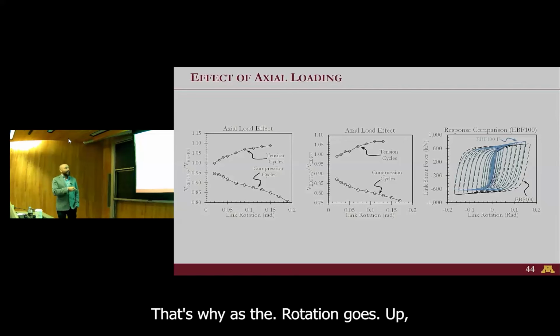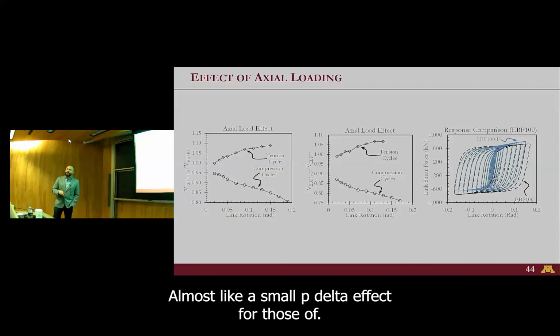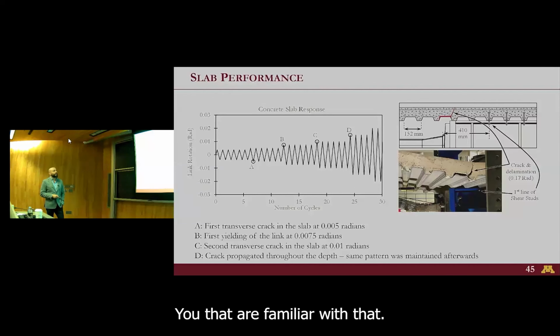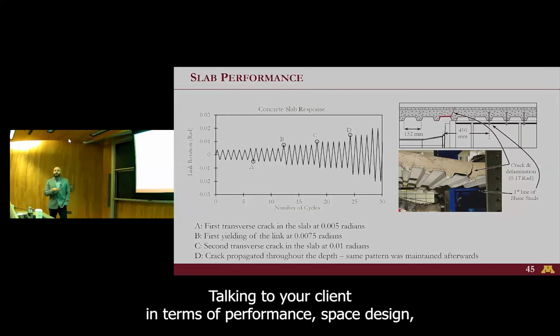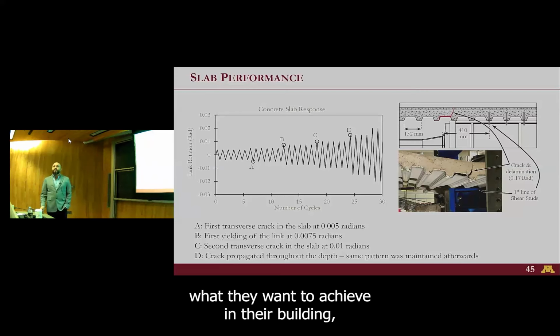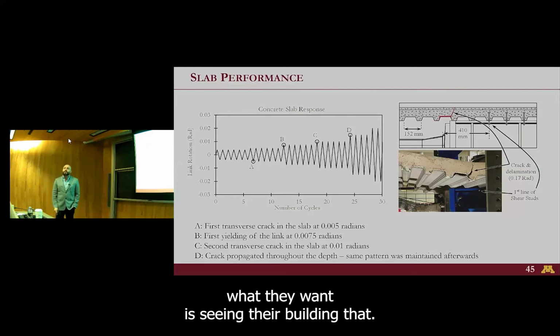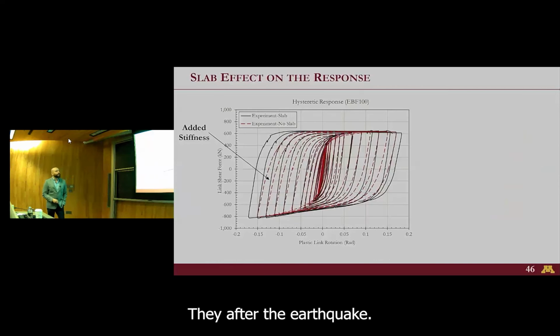That's why as the rotation goes up, this effect increases. It's almost like a small P-delta effect for those of you that are familiar with that. We were also able, like I said, to study the performance of the slab and identify damage indexes. These are useful if you're talking to your client in terms of performance-based design, what they want to achieve in their building, what they want to see in their building the day after the earthquake.